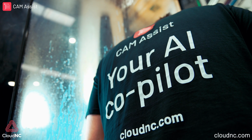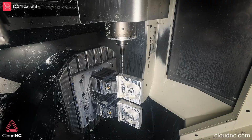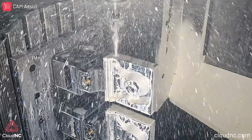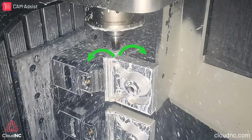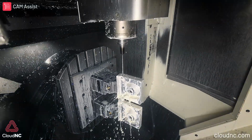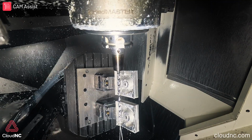The second is adequate feed per revolution. It is human nature to slow the feed rate down to be on the safe side. However, feed per revolution plays a big part in breaking the chip and forcing the swarf to exit out the back of the hole. If the feed per revolution is too low, the swarf will not chip and as a result wrap around the drill, causing it to break.